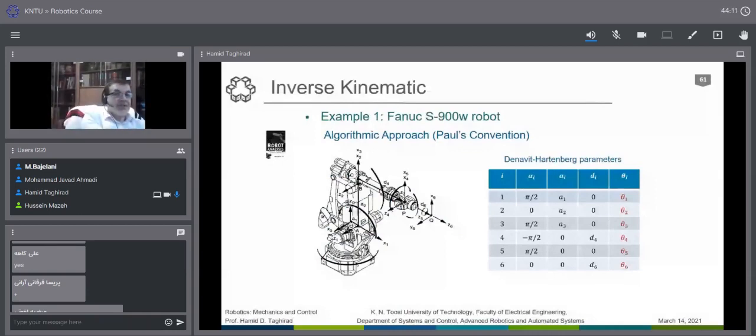So if you change the base rotation, this length or this radius is not changing. This radius is only changing by theta 2 and theta 3, the angle that we open our hand. And the rotation really doesn't give the difference in terms of the radius of the Z point in here. What does this give you mathematically?